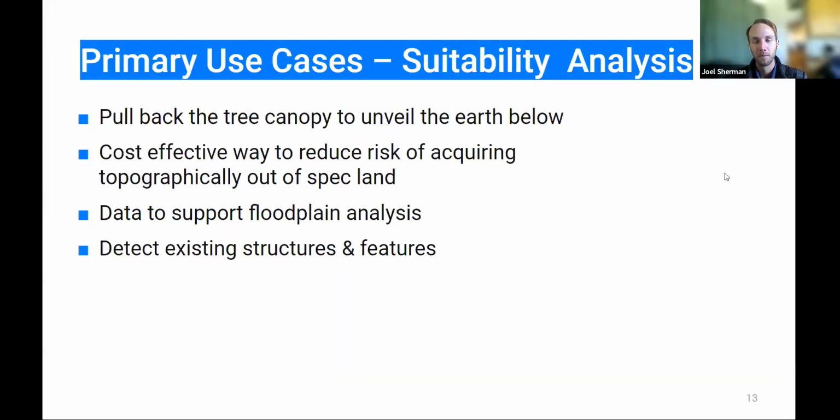All right, so that's the primary components of LiDAR in terms of its theory, its strengths, and how it's generally able to create these earthen profiles, so we're able to filter out the data and generate this specific original grade data set. Let's think about how that information, these original grades, independently of how they're derived, whether it's LiDAR or otherwise, can be leveraged to perform our normal workflows.